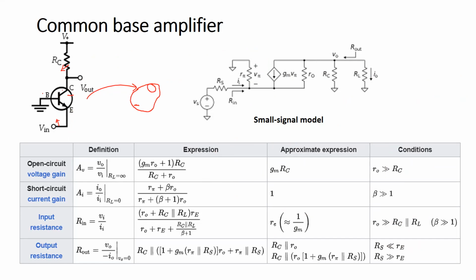Because you apply input to the emitter, actually you are also sourcing the current into the emitter, modeled by this I1. All right, so this can also be modeled as the Thevenin's dual, which is your Norton's model, right? Where you have a current source and in parallel with that you have a resistance, right? So you call it a RIN and RN. So this is your Norton's network or Norton's current source, which is a dual of your Thevenin's equivalent.